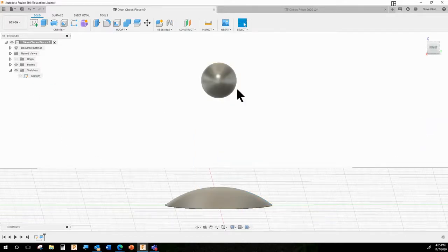And again, because I just created 3-dimensional material, it thinks I don't want to see my sketch anymore, but I do need my sketch to work with the rib. So I'm going to turn the light bulb on. So I've sort of made everything possible go wrong that could possibly go wrong to a beginner on purpose. So you can see all these things that are easy to fix because it's just guessing wrong.